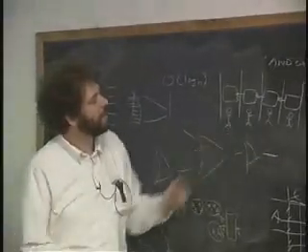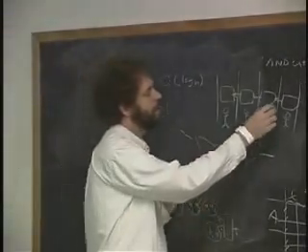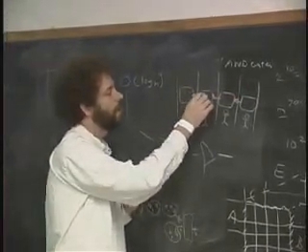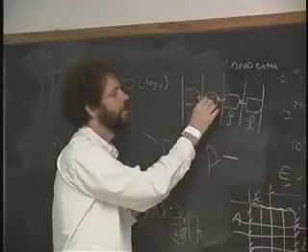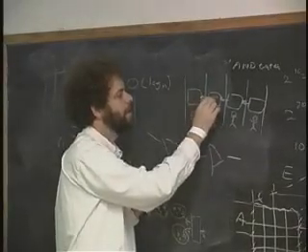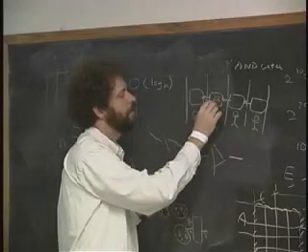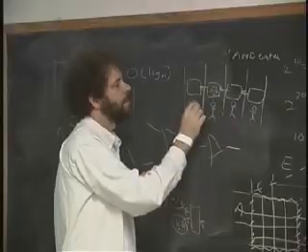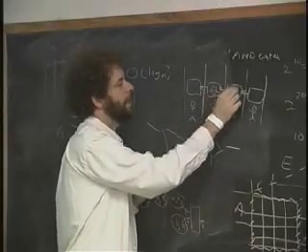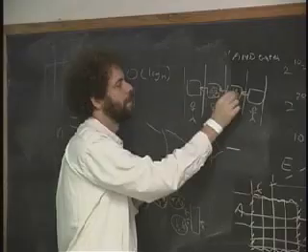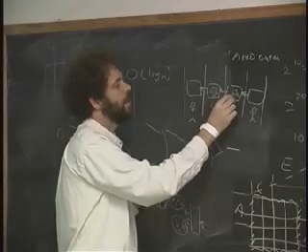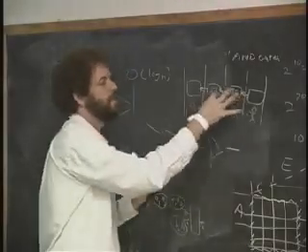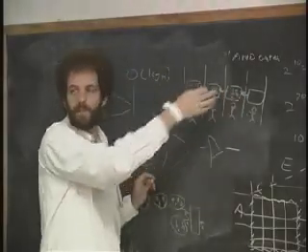And the idea here is that the add for a given number proceeds through the line in stages. And while one add is having bit number 20 done, so here's add, A plus B, and it's the add number K. The next one is having bit number 19 done, and that's A plus B, but it's a different A and a different B, and it's number L. Okay, and so each one of them is going to march through. And so we will pipeline.